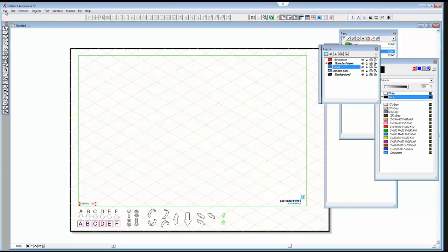We're going to do File, Open. And from the list here, this is a good example, actually, a good place to start and say, right, this is all the different file formats that we can work with. So at the top end, we've got our standard 2D formats, so our EPS files, CGM, Illustrator, and so on. Then we look at the 3D formats. So we're working through IGES, obviously PTC's own formats in here as well, the PRT and ASM files, STEP files, Parasolid files, VRML and so on. There's all the 3D data. Then we've got the raster formats, TIFF, JPEG, PNG.